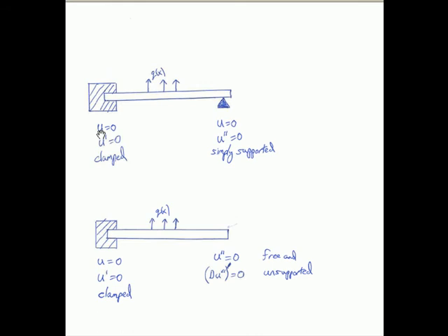So as for boundary conditions then, if u and u prime are given, the way I've got it drawn here, u is 0, assuming this is the u equals 0 line here, and u prime is 0, but they could be clamped higher up and with a different slope, but those are clamp boundary conditions. And so the flagpole is stuck in the wall as clamp boundary conditions. Q is the external force. If Q is negative, for example, the weight of the beam could just be a negative constant. These are called clamp boundary conditions. Those don't have to be 0, but whatever they are.